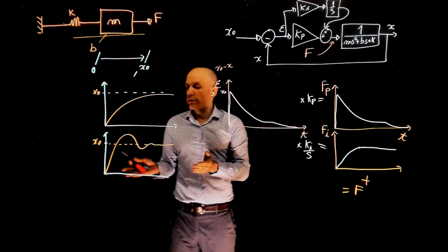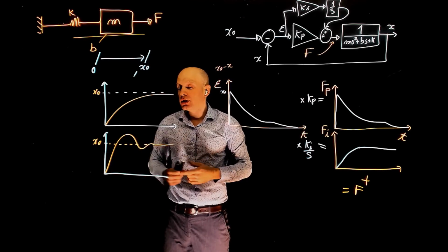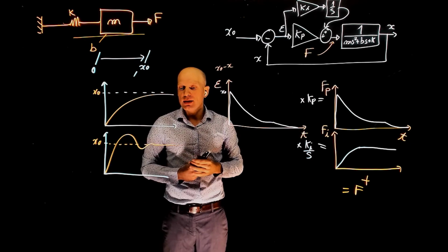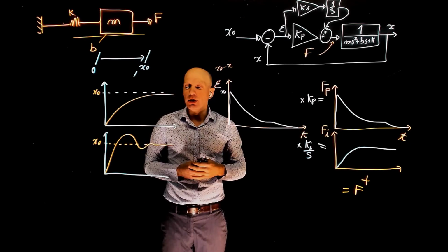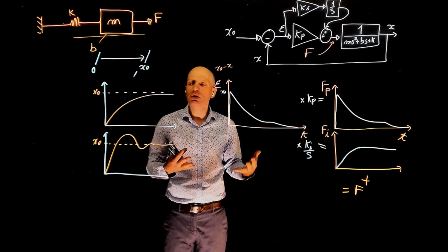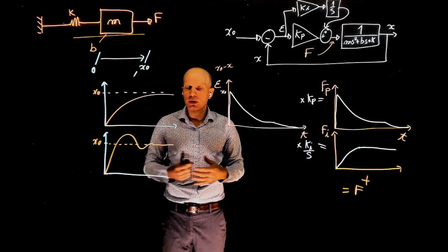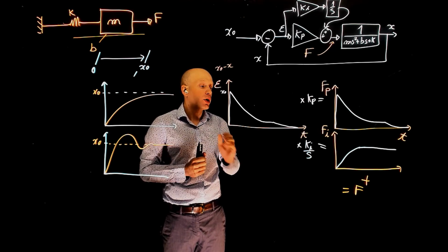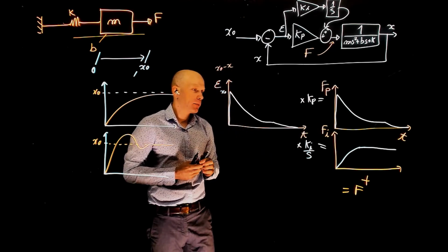How to eliminate this overshoot now? Well, that's where the derivative gain comes in. We covered that in the past examples, so I'm not going to repeat it here. This demonstrates the interest of having the integral component in the loop. It will always eliminate the steady state error, regardless of the value of Ki.